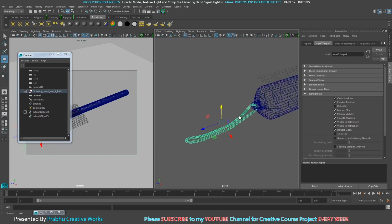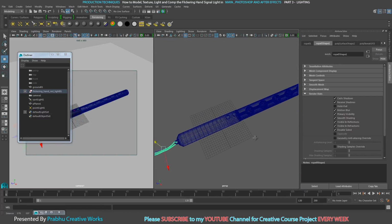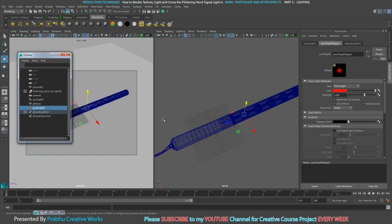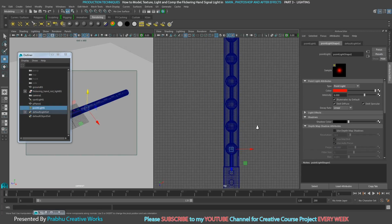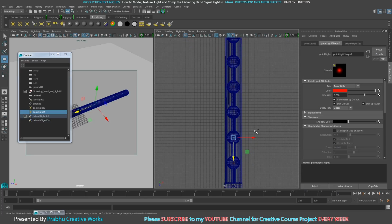Now I want to make many duplicates of my point light. So I will select my point light and go to top view. Now you want to duplicate up to here: press Ctrl D and move this one to the sphere. Press Ctrl D and move this one to here, press Ctrl D, move this one to here, press Ctrl